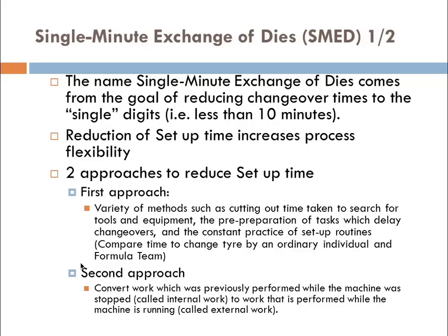The essence of the SMED system is to convert as many changeover steps as possible to external, which is work performed while the equipment is running, not when it is stopped. The essence also includes simplification and streamlining of the remaining steps.